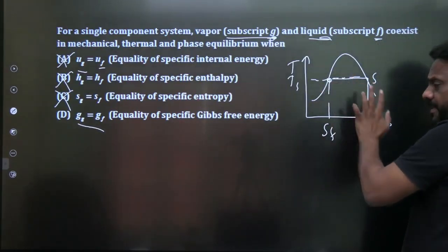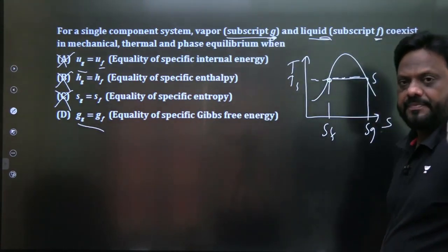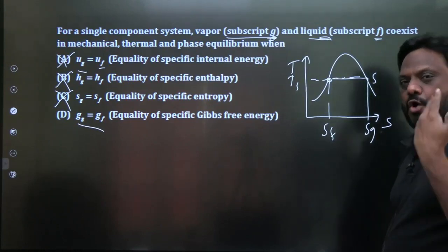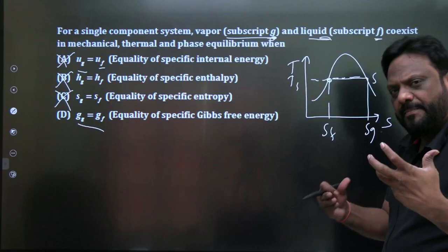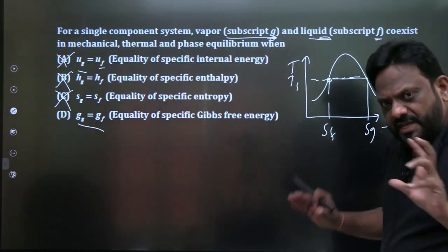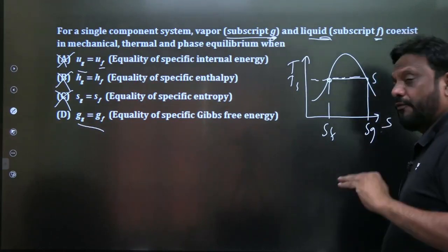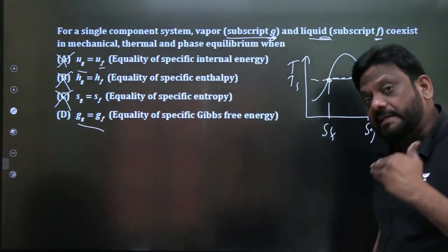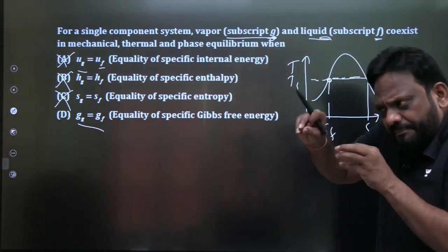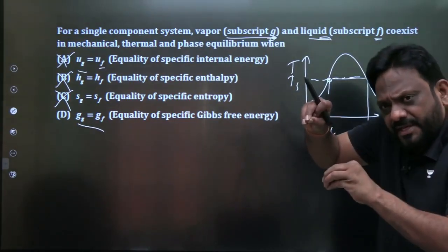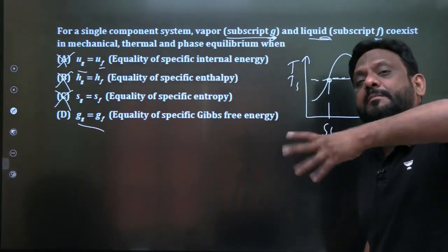My liquid and vapor are at the same pressure, they are in mechanical equilibrium. And there is no change in composition if it is water, liquid H2O and vapor H2O. So there is no change in chemical composition. So therefore, now all are in equilibrium. So therefore, phase change is an internally reversible process, because whenever you are heating, every time internally the liquid and vapor temperature and liquid and vapor pressure is absolutely the same. They are in equilibrium every time during the phase change.